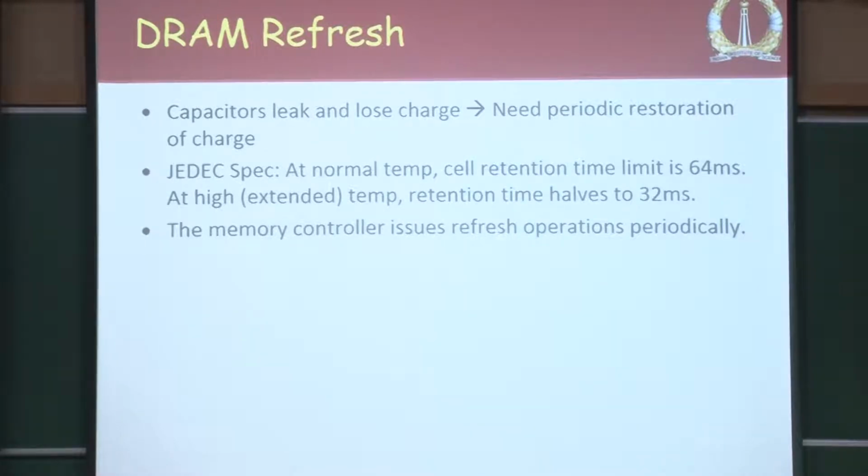A single refresh might take something like 20 cycles. I am going to use the word row and page somewhat equivalently. When I say row buffer hit, it means that the particular row or page is there in the sense amp, because they use the term page also in DRAMs. But if you are comfortable, we can stick to row.